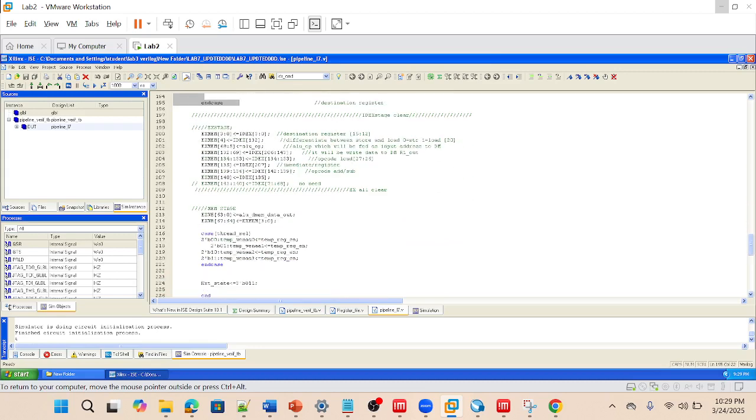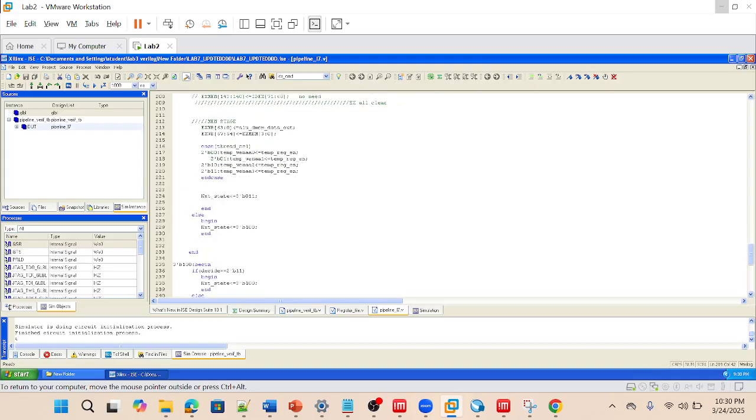Also at the end, in the write back operation from the fifth stage, we know that the address and data will always be coming. So instead of modifying that, I drive the same address and data to each of the inputs, and only the enable signal distinguishes which operation we need to perform. These were the three major changes that I did.